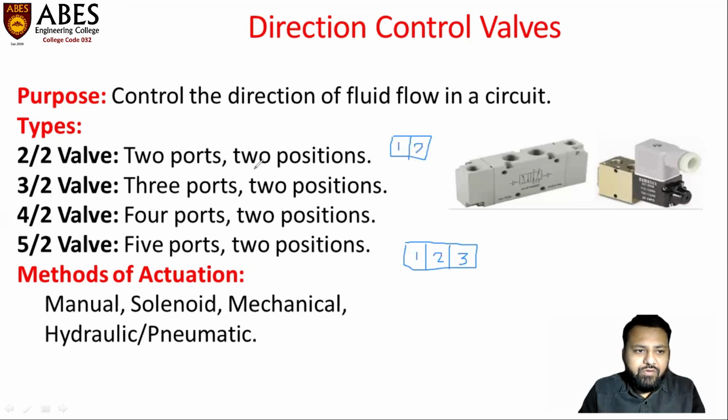When we talk about the ports, we have some ports over here to supply the fluid to the cylinder and to the reservoir. So if we have four ports, this kind of valve is known as the 4/2 direction control valve. Okay, hope this is clear to everyone.